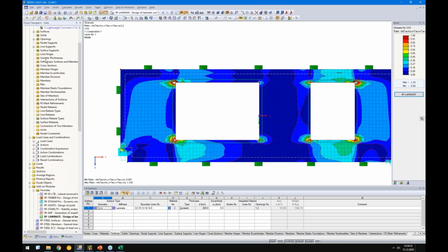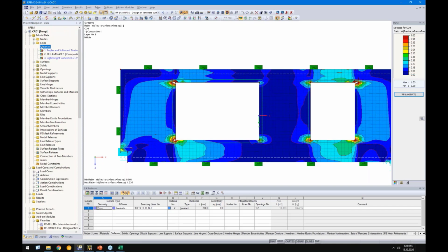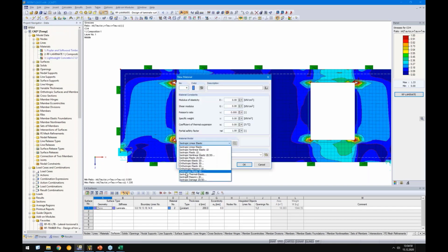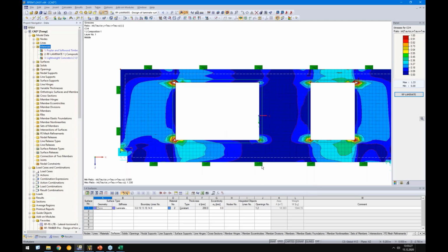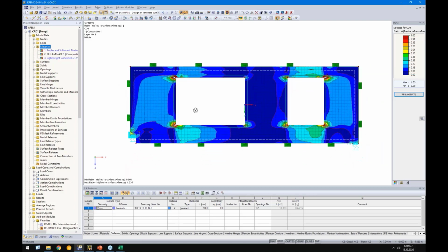We have here a solid called new material model called orthotropic plastic 3D, but this is not the wished design for this simple wall element, because it is much more. So you need to define just the strengths, the limits, and of course you need to model the slab or the wall element as a solid element. So each layer needs to be modeled separately. You need to consider to model the gap because of the glue on narrow sides or no glue on narrow sides. This is not a practical way to do this.